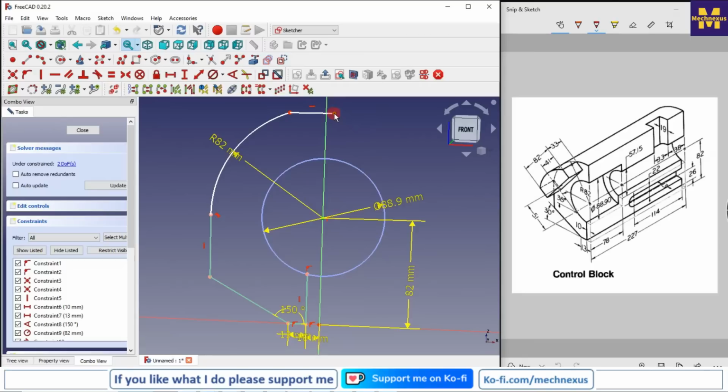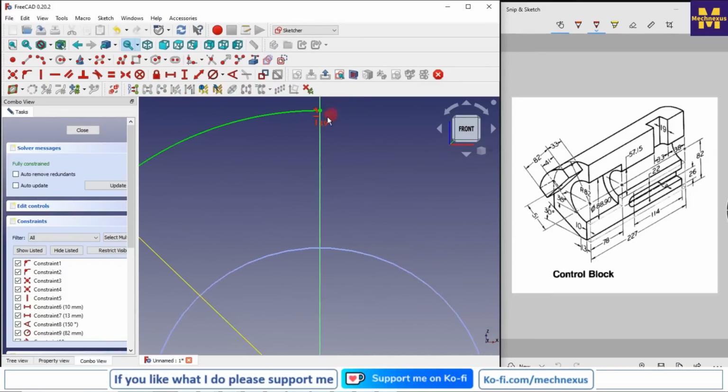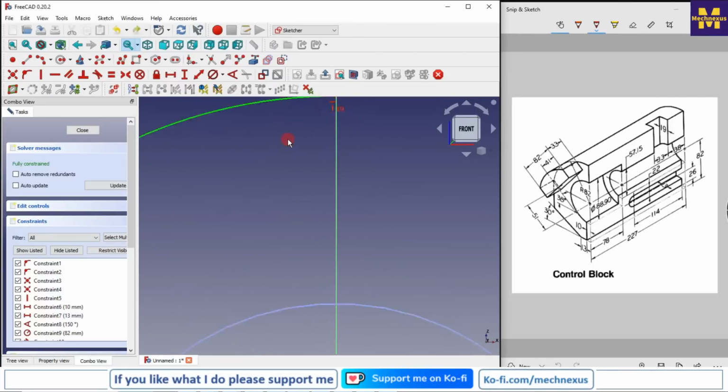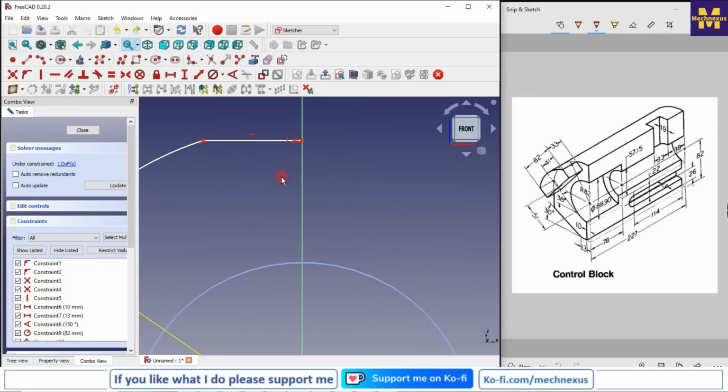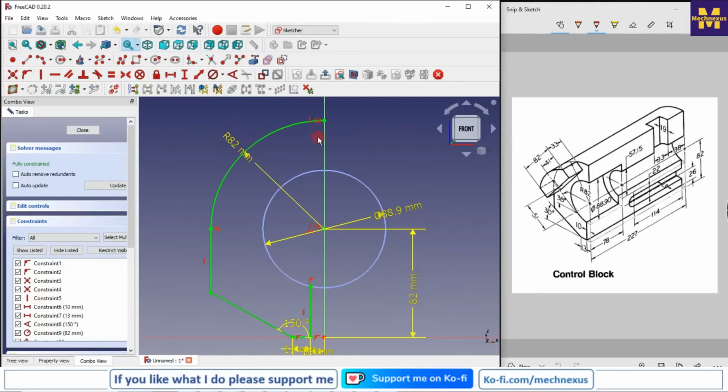and now I will make these 2 points vertical. Okay, and here I will add the tangent. So I will delete this line because it is not required, and I will give this and this vertical constraint, and I will join the line. Now I will give it a vertical constraint, and as it is a construction, I will remove its construction and trim it. Now I will go with the trim tool and trim it.